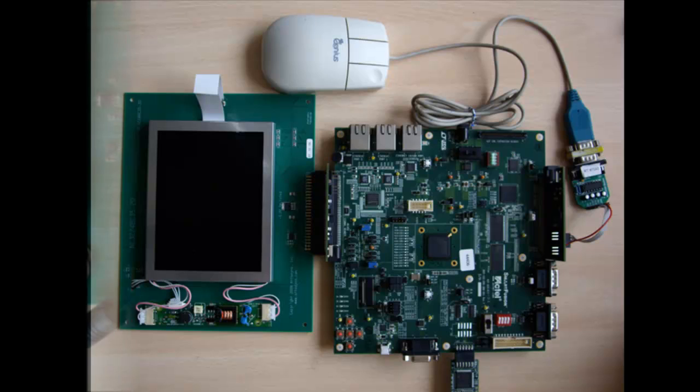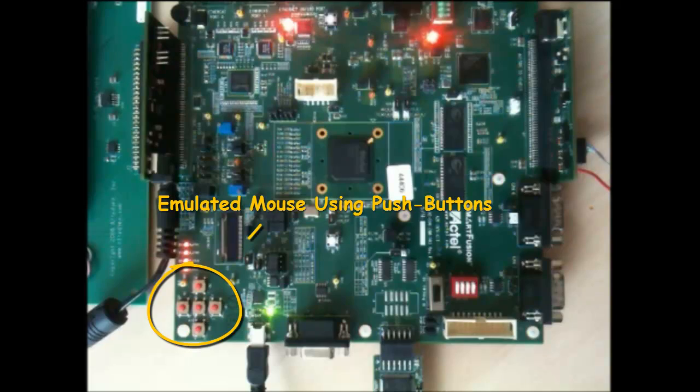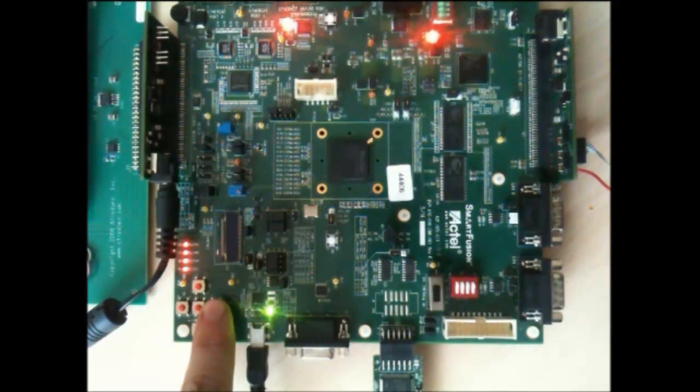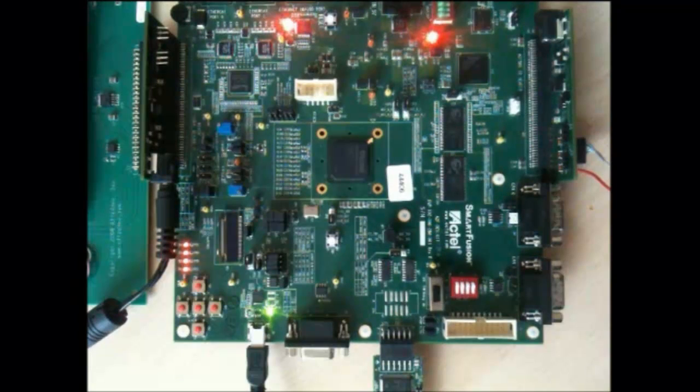For the input device, this demo uses an emulated mouse device using the 5 push buttons available on the Microsemi board. The left, right, up, and down buttons are used to emulate mouse movements, and the center button is for mouse event clicks. This type of mouse is not very convenient since it takes a lot of button pushing to move the cursor to a desired location. You will see in the demo that the mouse cursor moves around slowly and somewhat awkwardly. However, this is the only input device that is readily available on a Microsemi board, so we're going to go ahead and use this for the demo.